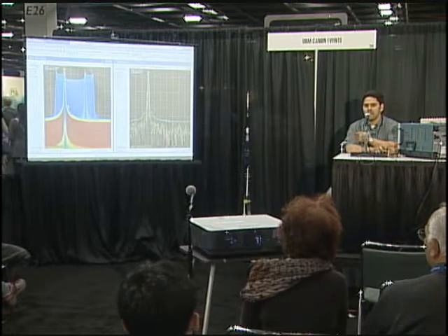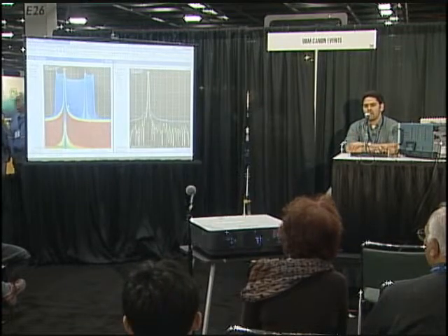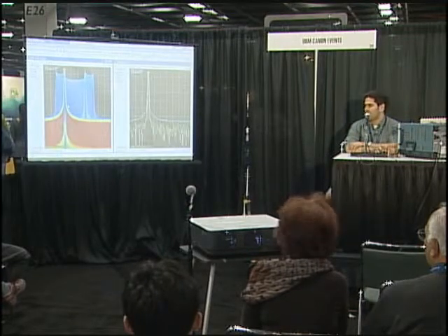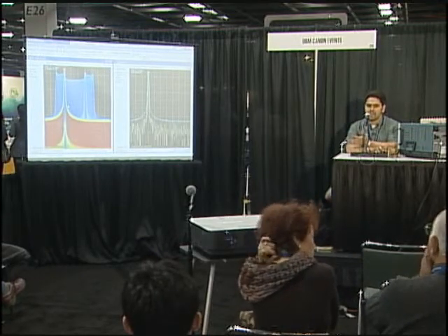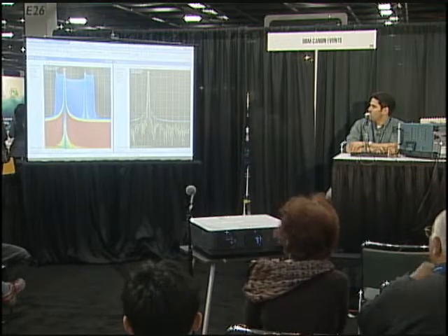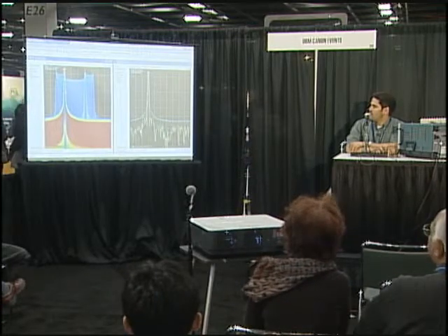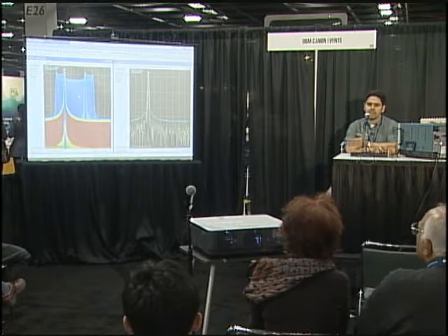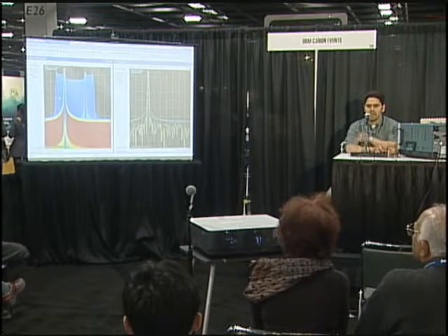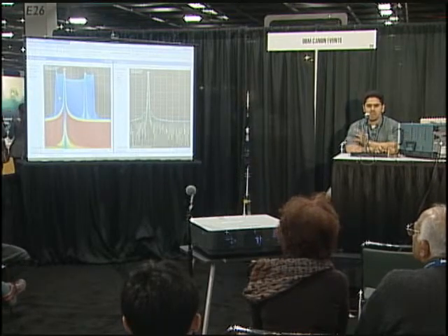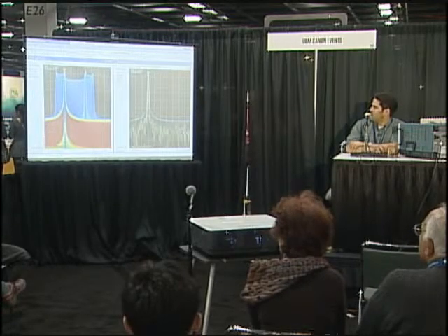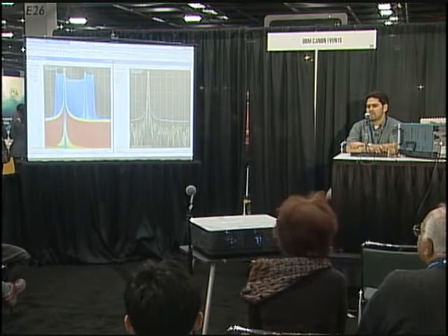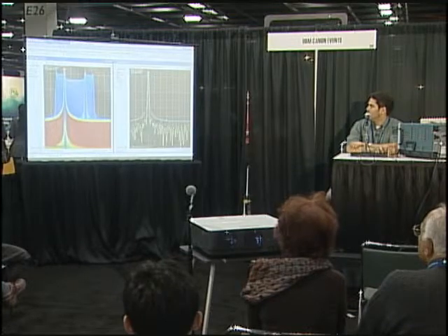So you can see the whole behavior of the signal with this DPX display. The colors then give you an idea of where the signal is spending its time. But we still don't know, for example, if it's spending 100 microseconds or 1 millisecond, or if it's happening every second or every 3 seconds, right? We just get a relative idea based on the colors. So what we're gonna do next is use the rest of the tools on the analyzer to find out all those questions, to get all those answers.